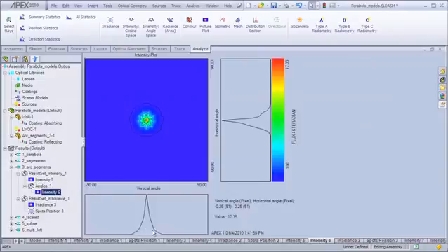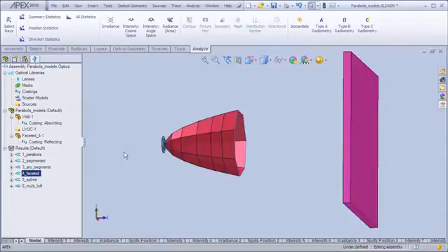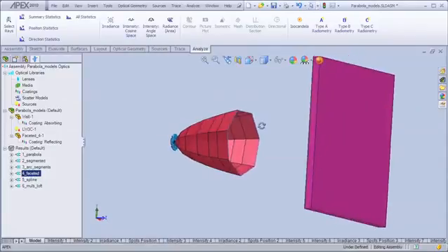So if we were to move our detector or try to illuminate at a farther distance, we would see that the light would start to drop off quite noticeably. And we also see some information relative to how the angles at each facet edge affects the light. And if we were to count these, it would be an easy way to see how many edges I had put on my polygon. In this design, we've broken our parabolic section into linear segments, and then we've also swept those based on the polygonal output face.